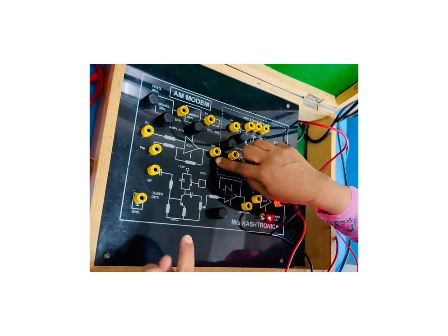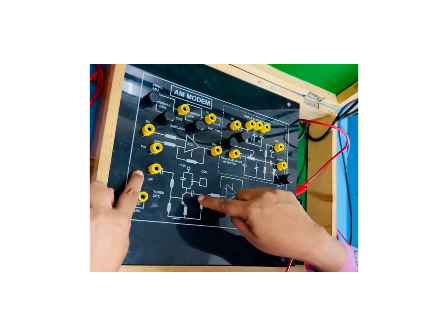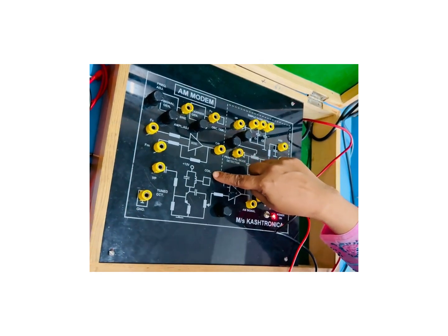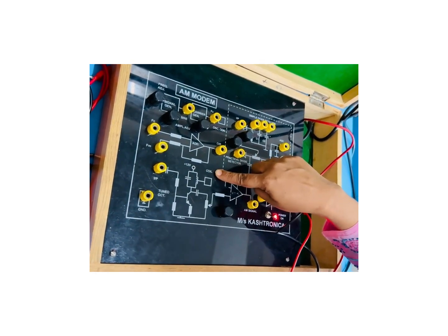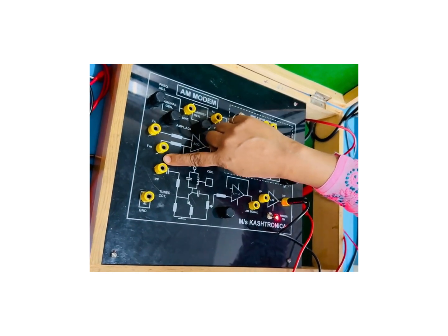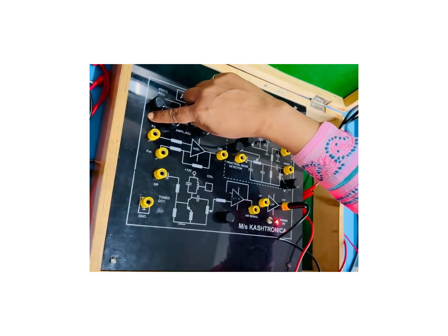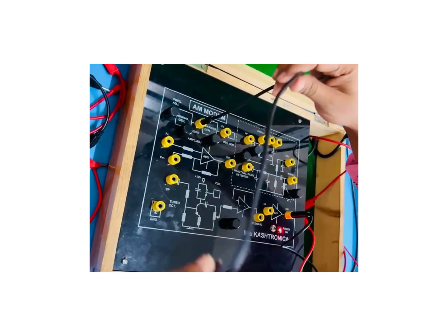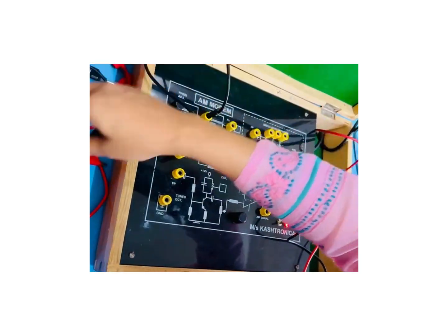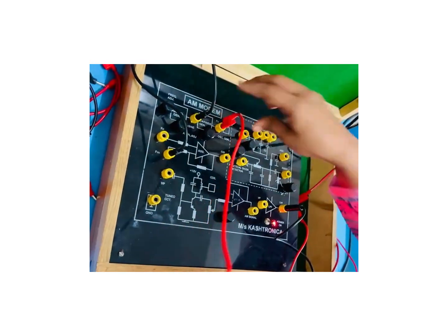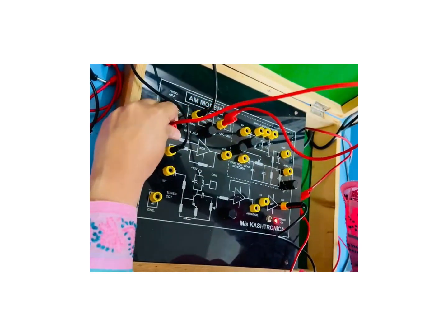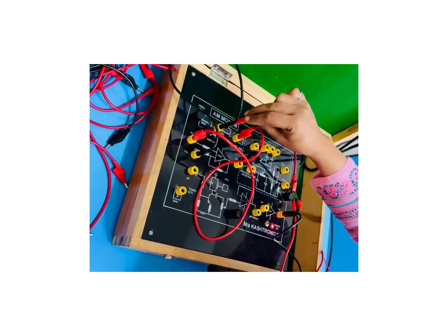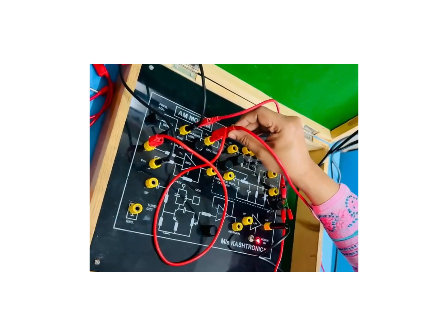Output of adder is to be connected to the input of tuned circuit, which generates a fixed frequency or high frequency carrier signal, and its amplitude will be modified or modulated with respect to the addition of amplitudes of FM signal and FC signal. So let's observe this first. I am connecting the modulating signal to the FM input of adder and the carrier signal to the FC input of adder. Before we proceed, let's adjust the amplitude and frequency of modulating signal and amplitude of carrier signal.